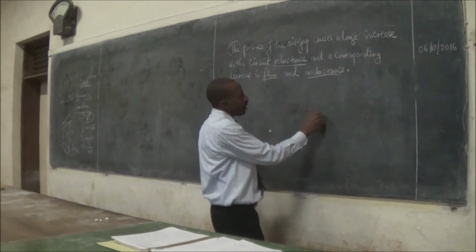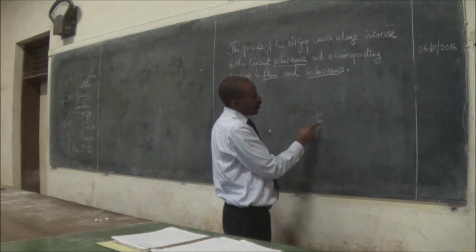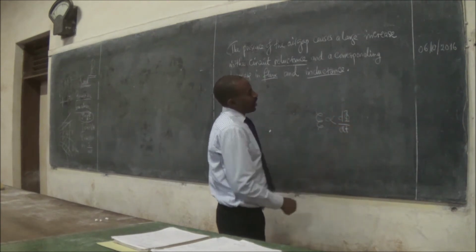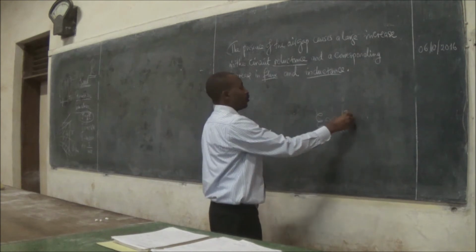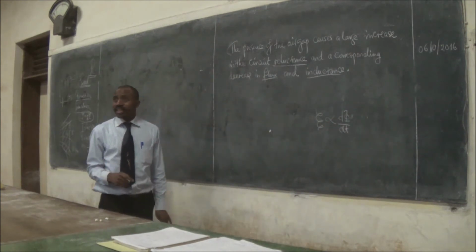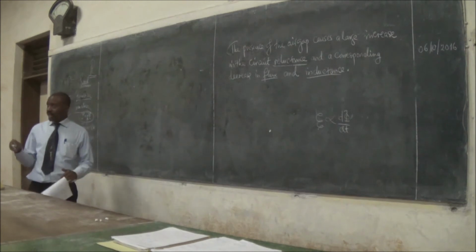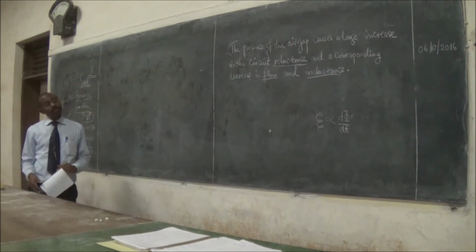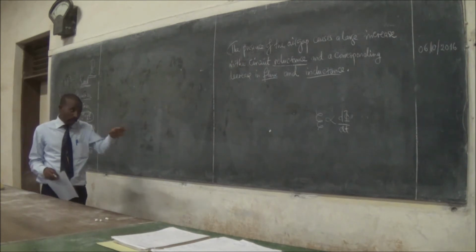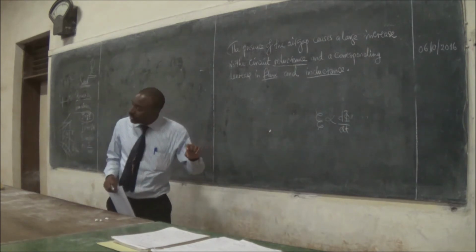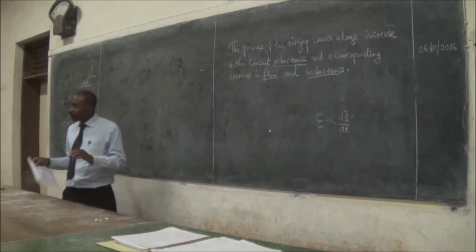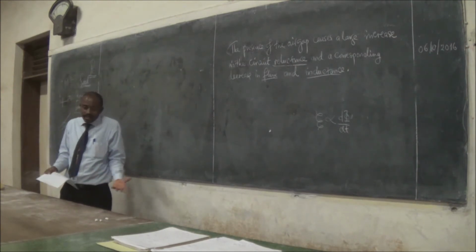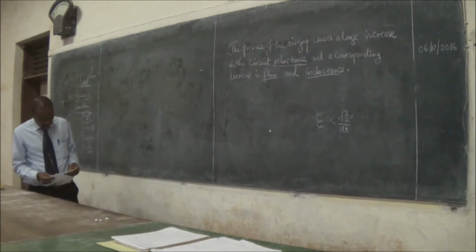For example, if you have your flux, then the induced EMF is proportional to the rate of change of flux. Now, if you can do this, that means you can change the induced EMF. If you can either increase or reduce the flux, you can change the value of the induced EMF. And then you can create sensitivity, and you have created a sensor. Where there is sensitivity, you create a sensor. Anything that feels any sensitivity is equally a sensor.